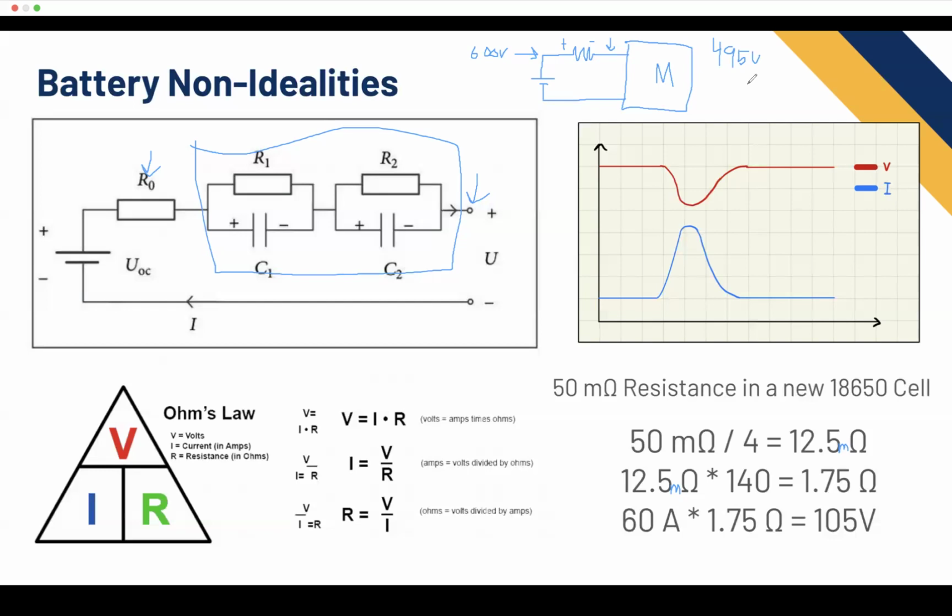So the issue you run into is what's the minimum operating voltage of the inverter? How low does that voltage go before the inverter shuts off? And the answer is a lot higher than we would like it to be.